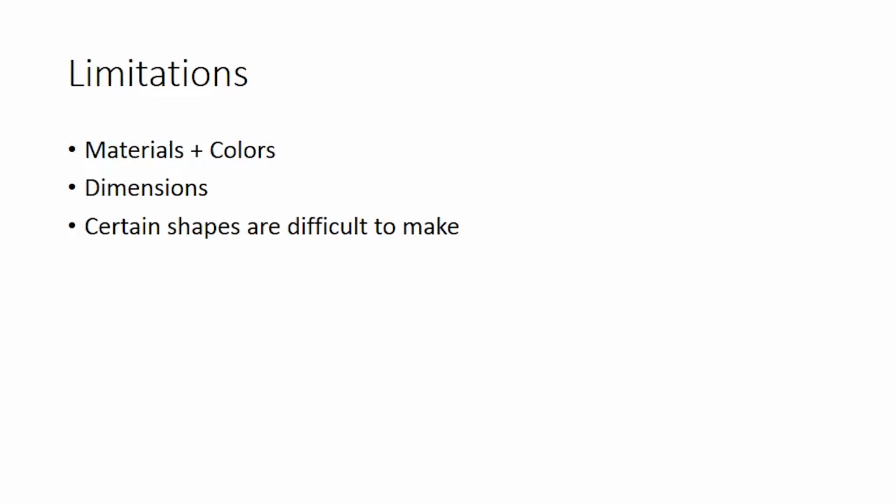So that you can only print something so big, right? But you can also only print something so small, right? Yeah, feature sizes. So this is an issue that has to do with the extruder. And this is something that you want to keep in mind when you're designing parts for 3D printing: know the limitations of your machine.